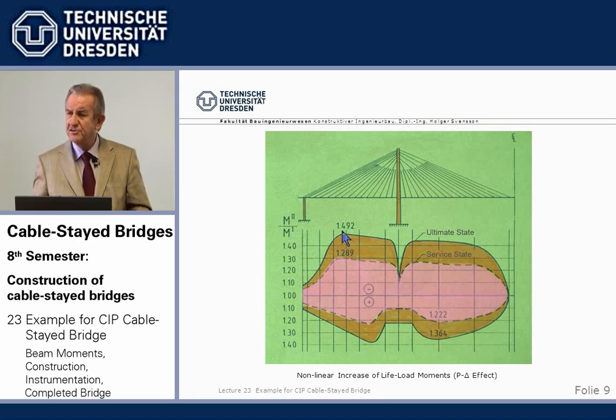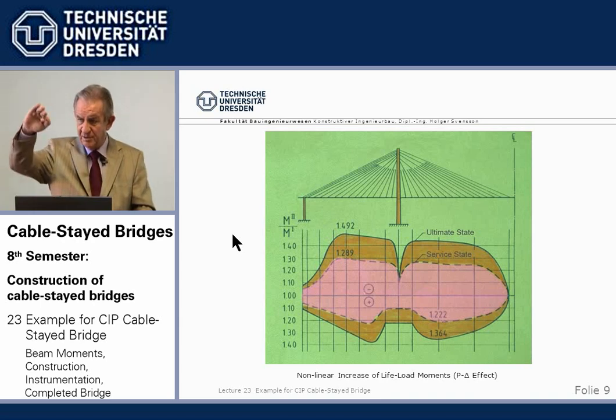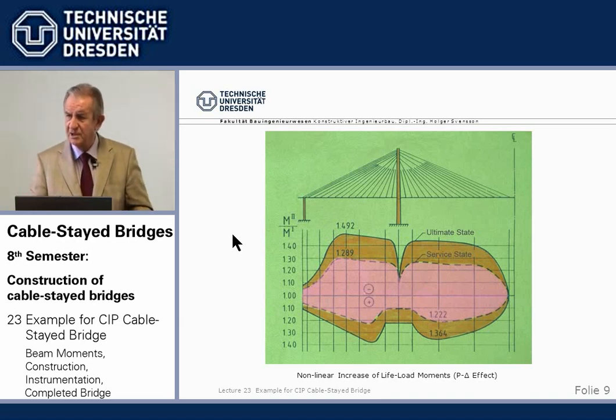And that also shows you we are here at a limit, because that goes up exponentially, and when you go beyond this, it goes up very fast. So you cannot be more slender either from statical nor from, in this case, wind resistance than this 1.2 meter beam.